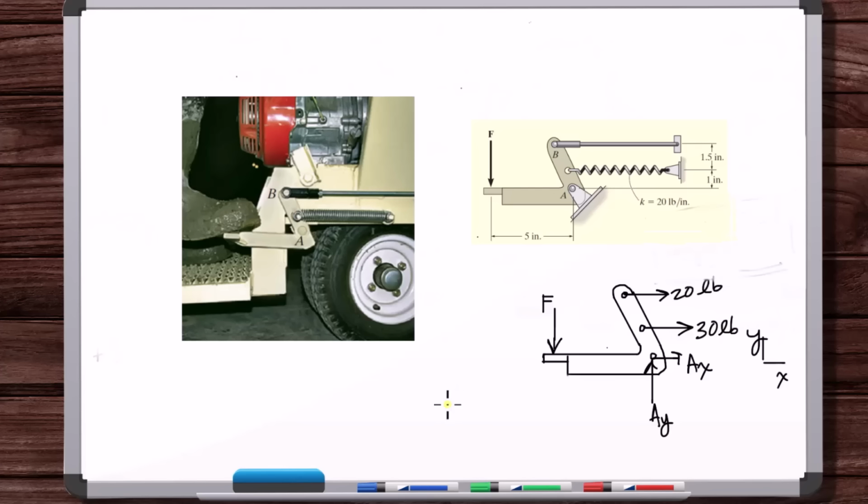And in addition to that, the second requirement is that all of the forces, known and unknown, need to be symmetric with respect to that center axis plane. And then third, all of the forces can't have any components that are perpendicular to that center plane of symmetry. And then fourth, if there are any couple moments, then the direction axis of the couple moment needs to be perpendicular to that center plane. If those requirements are met, then you can project all of the forces onto a single plane. And you can think about that plane as being that symmetric center plane.